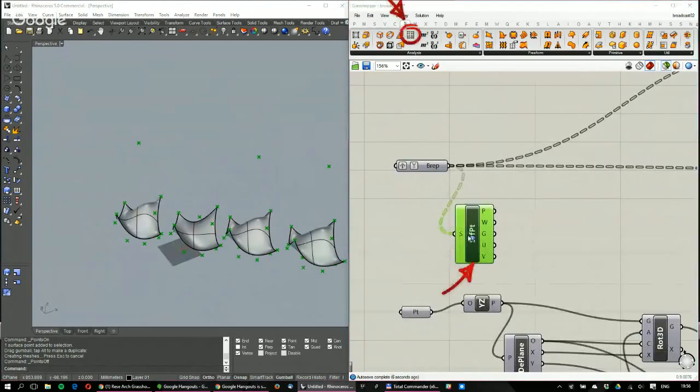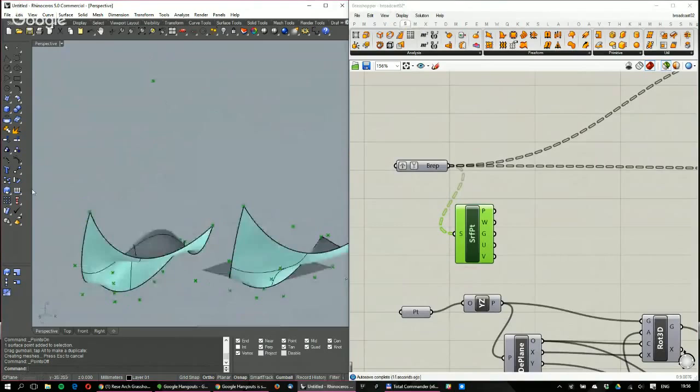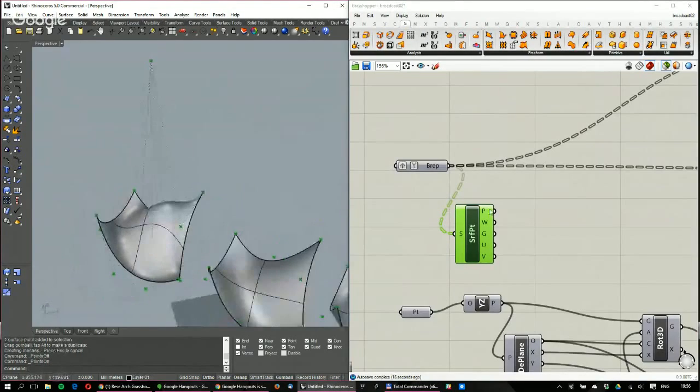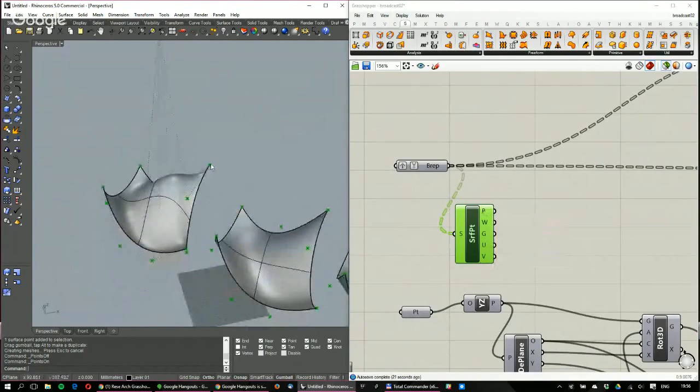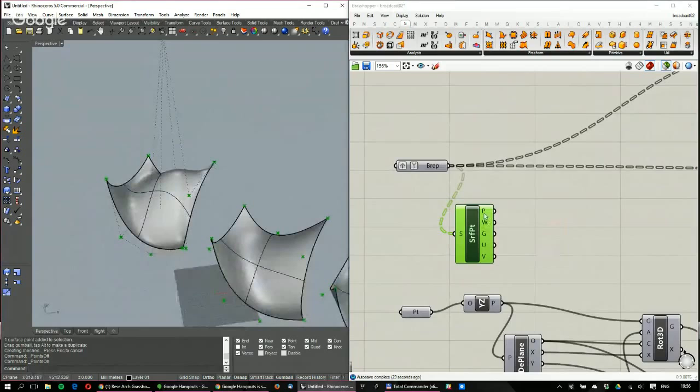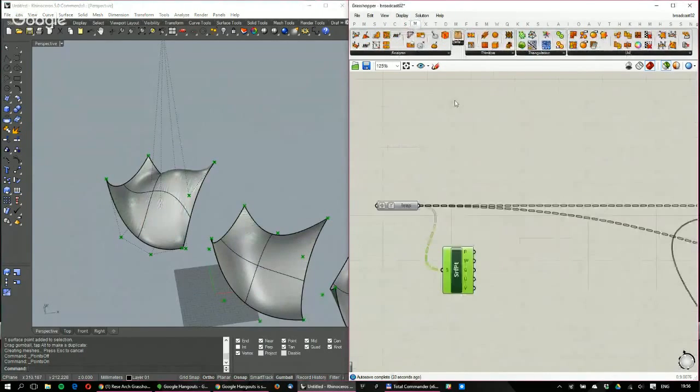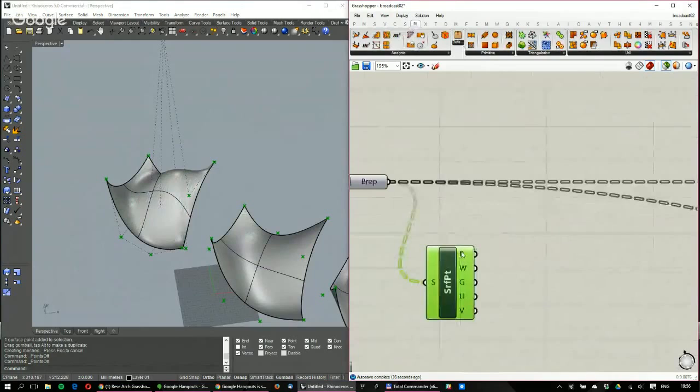So it's called surface points. And it gives a surface, and you see they're perfectly matching with these control points here. So these are actually the points of the polygonal hull, and there are 16 for each one, which works well because it's 4 times 4 control points. Using these 16 points, I can regenerate a mesh. This is going to be slightly messy, but nevertheless, I'm going to do that. So now you see that there are 16 points, and they are not really sorted anyhow.